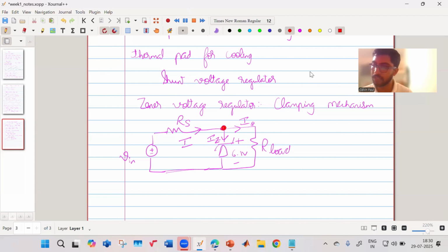Okay. So that is first of all not desirable. If there's isolation, it won't propagate, but if the isolation is not there, it can propagate. So the Zener diode is there. It will filter out the fluctuations. Okay, it will act as a protection. So in case, by some chance, the voltage goes high, it will clamp that voltage.